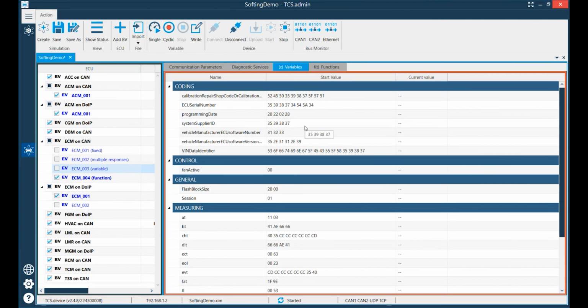It's very useful if you try out different sensor values, 20 degrees, 22 degrees, if you want to work the ODX way and see what the tester system is showing you on this side. So this is one way: using the variable and changing the values during simulation.